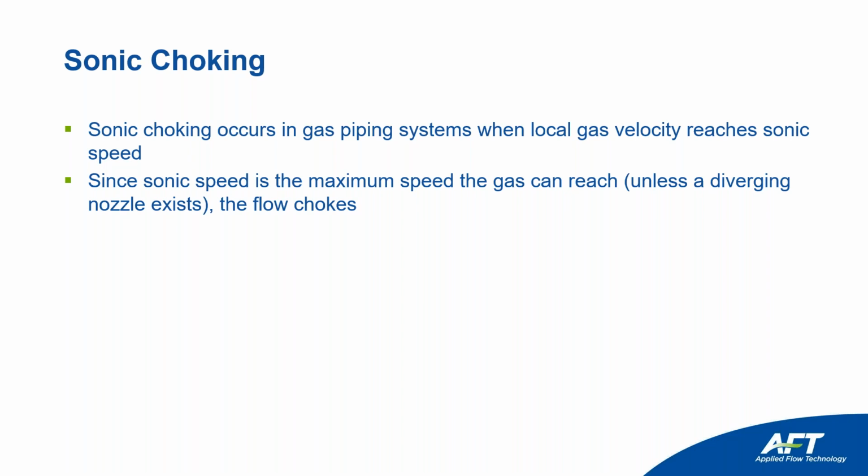It's not able to go any faster than that unless you have a very special type of geometry, like a diverging nozzle, and then converges. And so basically, when you have sonic speed, then the flow is going to choke.